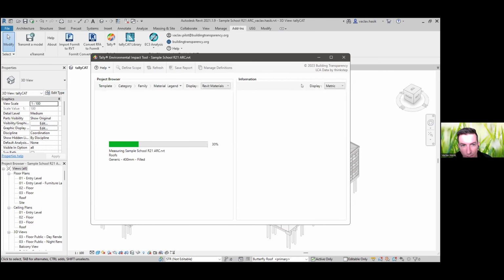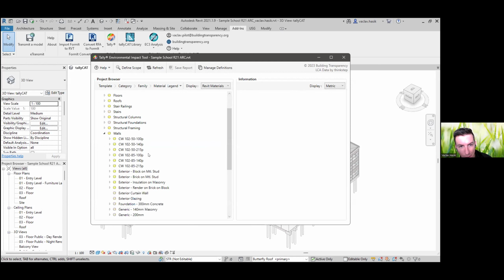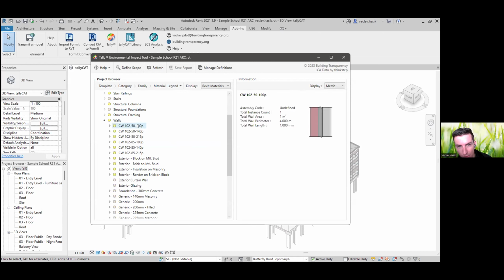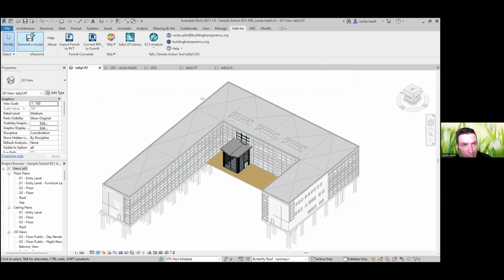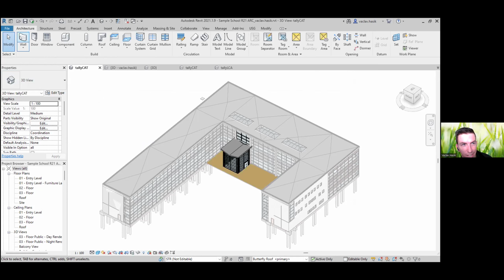So at this point, you can go and apply. Now this might take a little bit longer. Okay. Now you can see that previously all of these were green, but not anymore. Why is that? Well, because there are many other wall families that I can actually go and select from here on the left side. For example, in the architecture tab, go into the wall sections.